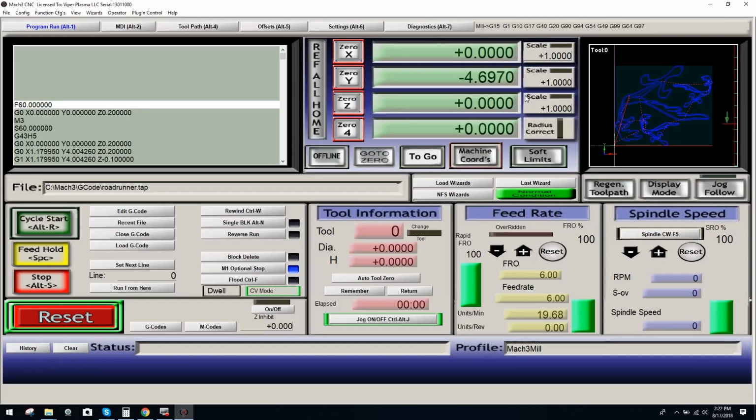Now I have guys that'll say, well, I'll just put my measurements in instead of doing this. And you can definitely do that, but you better be damn certain you're right, because if your measurement is off you're going to have to reset it anyways. That's why I like to just jog it. Sometimes doing the manual work, it just cuts you down time on the opposite end, so to speak. So now I'm happy with where the Y is. You'll naturally stop 1 to 2 inches before your Y's end stop on negative travel, and we will zero it.